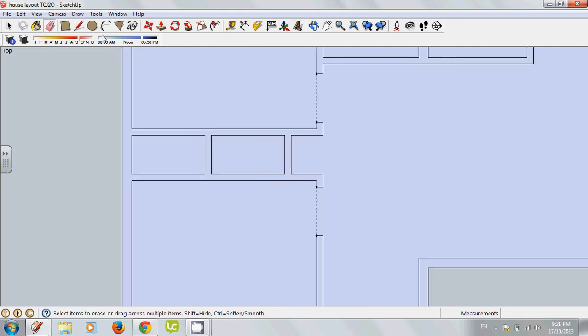And then in these bedrooms, we are going to come in 5 inches on each side, and that's going to allow us to put in, if we measure this, it's 36 inches, which is sort of an easily found bifold door that can be used for a closet.